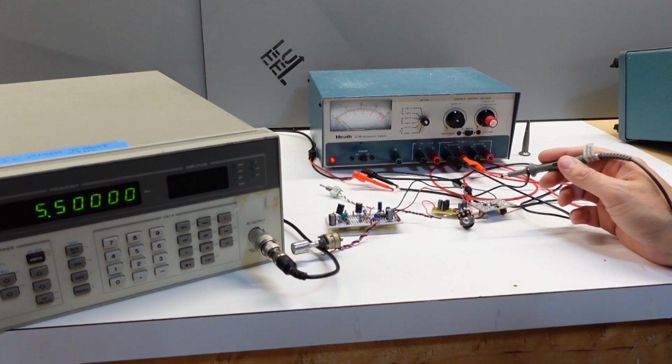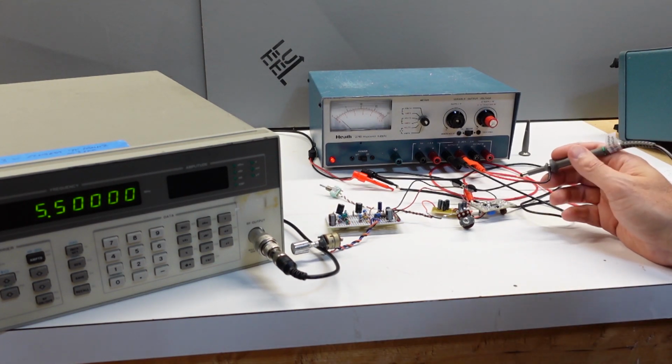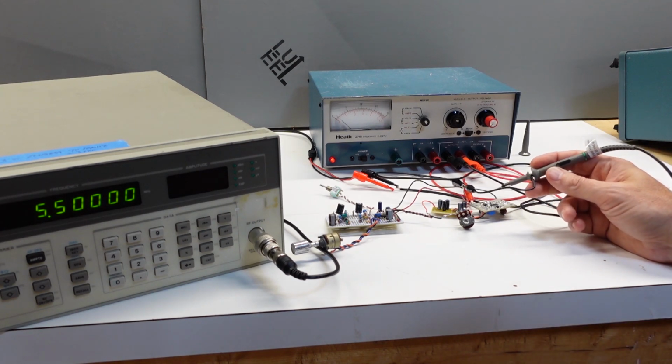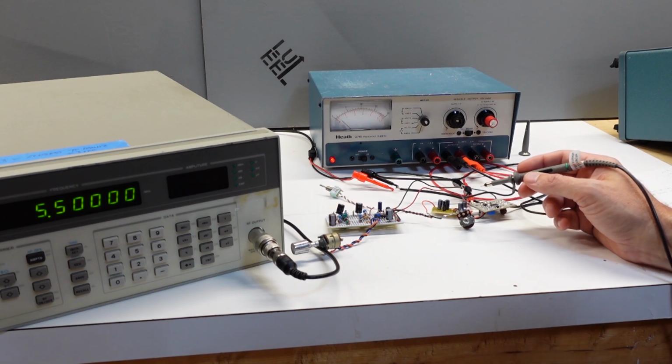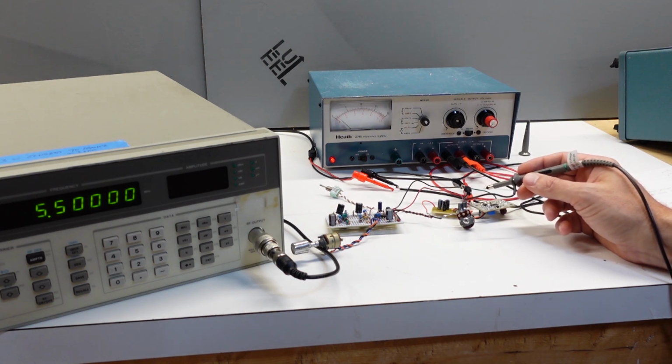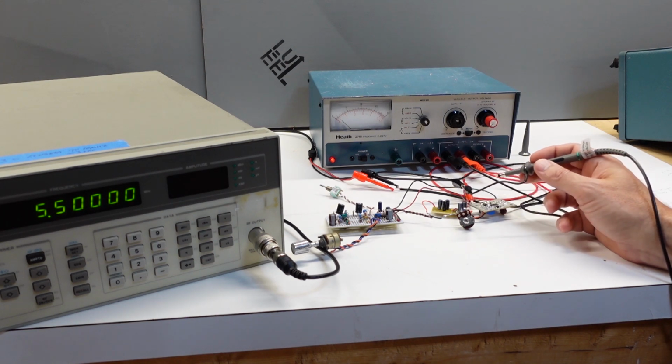Alright, so I'm going to go ahead and set the signal strength for the carrier signal now. As far as setup goes, the other details: I have my 10x oscilloscope probe, and the 465 I have set to 5 millivolts on the vertical scale, so it's really reading 50 millivolts per division, and the time base is set to a tenth of a microsecond, I think. So we should see a good sine wave on there.